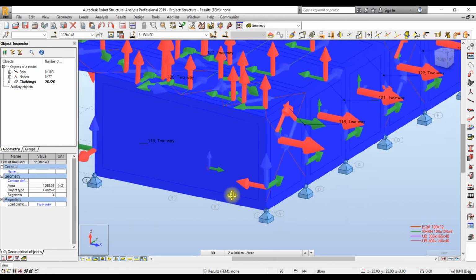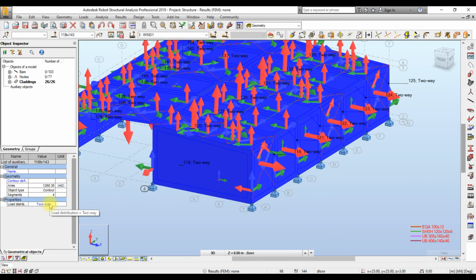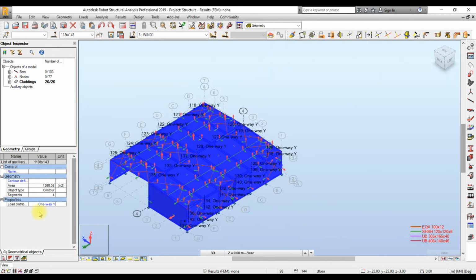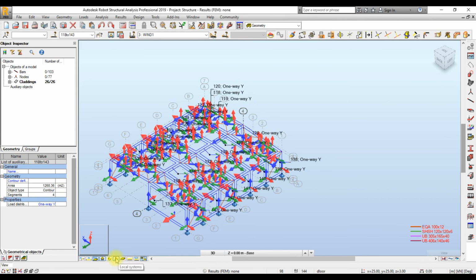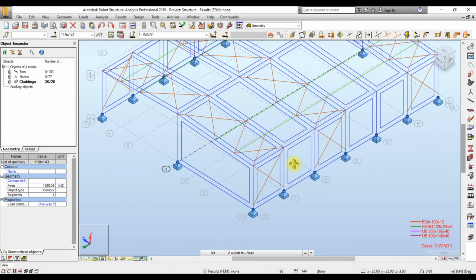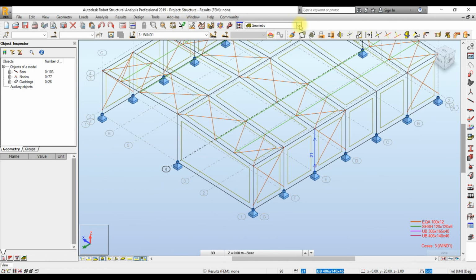Okay, let's give it to this X. Okay, and then Y. Okay, so now you can just hit off your panel description and other stuff, panel interior, panel description, local system. Okay. So now you come to our loads.